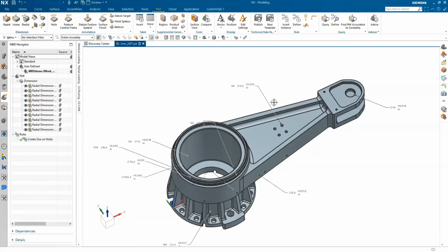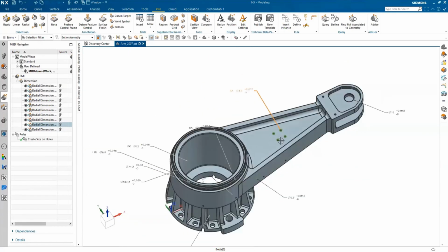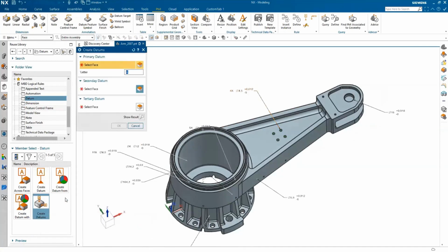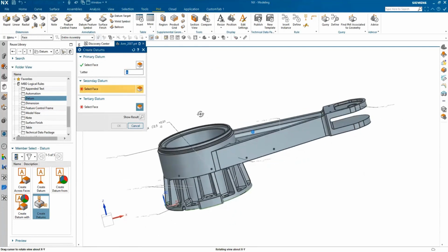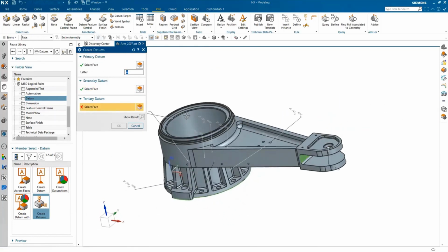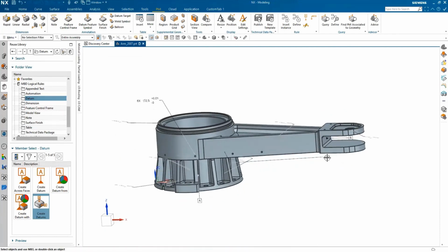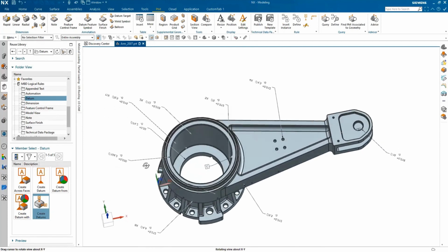I picked the model, it inquired, it found everything. So it knew what geometry goes along with that, right? And this is important when you use it downstream. Also knew the count. And again, the tolerances that we put, the fits that we actually selected there. So other things that you might use might have a little bit more interactive, right? The first one was pick the body, it does everything. In this case, we were creating the 3 datums. We did have a set of input, but now it's done. It has those datums created on the part file.